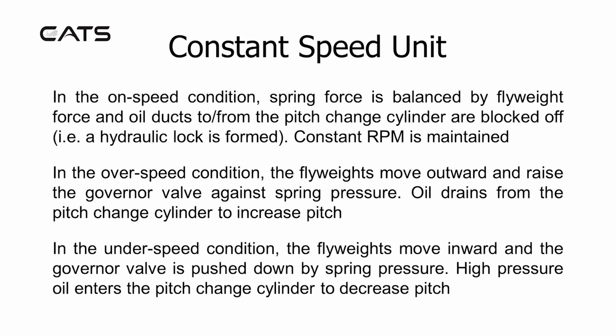Oil drains from the pitch change cylinder to increase pitch. In the underspeed condition, the flyweights move inwards and the governor valve is pushed down by spring pressure. High pressure oil enters the pitch change cylinder to decrease pitch.